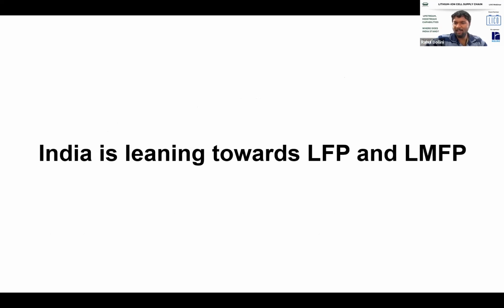India is leaning towards LFP. Just before the webinar beginning, I was talking to the recycling guys also. LFP is going to be it, for the simple reason it's cheaper, it lasts longer, it is safer, and it can work in higher temperatures. And India does not lean towards the colder temperatures, although we have some states, some places. LFP has a drawback. It cannot charge easily below 0 degrees Celsius. But there's a solution where you attach some heaters and bring up the temperature, but that's going to waste some energy and increase your charging time. So LMFP is a new kind of LFP, which, like I told, Tesla, CATL, the big guys are talking about, soon to come in the market.